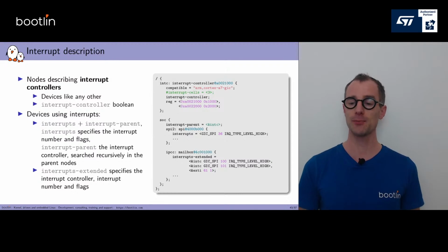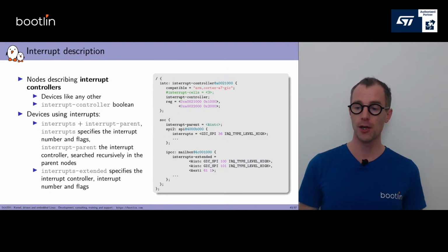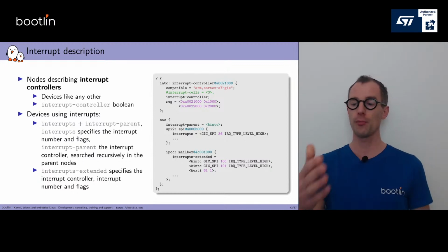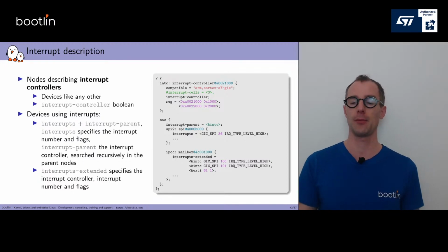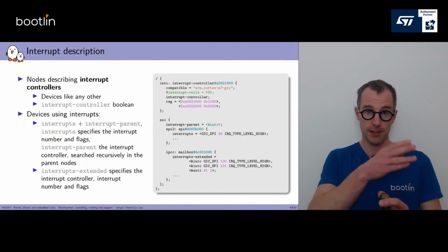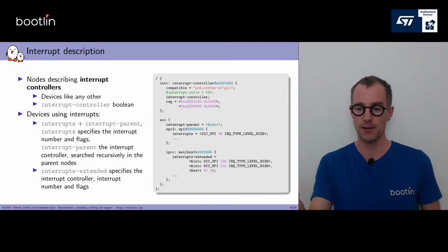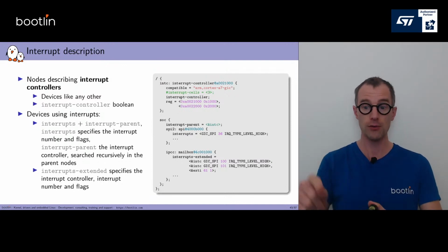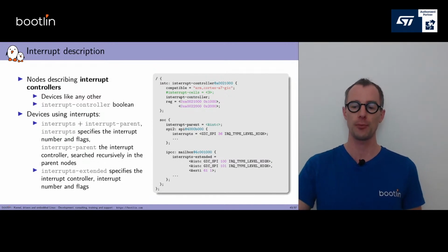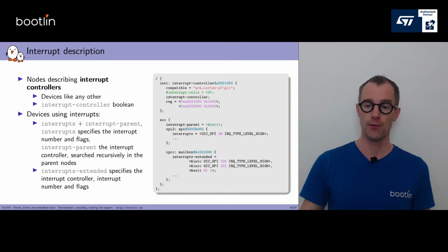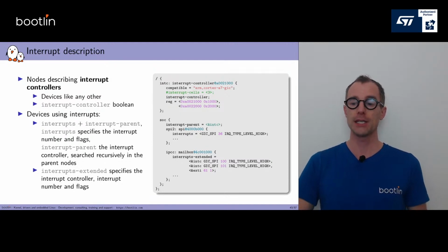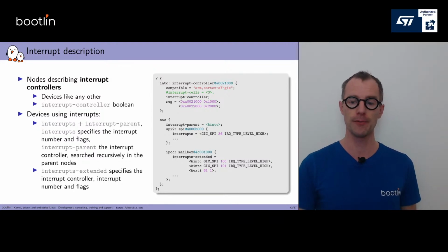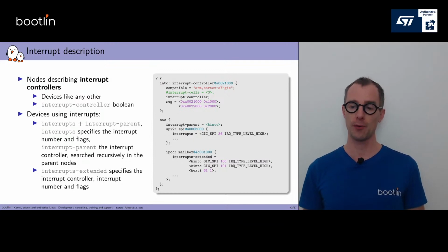Right, so when this SPI controller says GIC_SPI 36 IRQ_TYPE_LEVEL_HIGH, it gives the type, number and flags for an interrupt. And this is 3 cells, right? GIC_SPI, 1 cell, 36, second cell, IRQ_TYPE_LEVEL_HIGH, third cell. So we match with this #interrupt-cells property. And this interrupt specification is related to the interrupt controller identified by the node that has the inc label because of this interrupt-parent property.